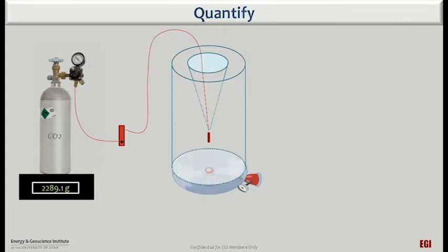A CO2 canister was placed on the scale, detailed in the equipment section, capable of recording the weight of the canister at certain time intervals. Attached to the canister was a pressure regulator and a rotometer controlling the volume of flow into the system. A tube was run through the top or side of the vent and terminated in a diffusion device to ensure equal radial CO2 release. A fan at the bottom of the cylinder blew the CO2 infused air up and out of the vent annulus, just as occurs in the Union roof vent.